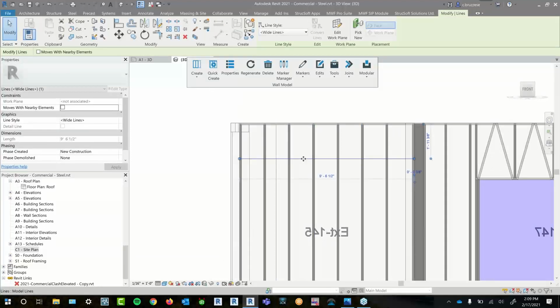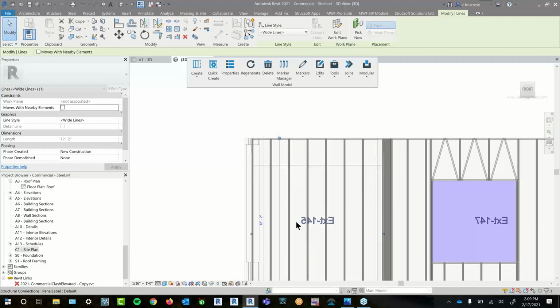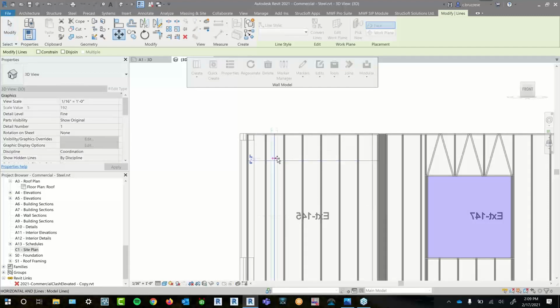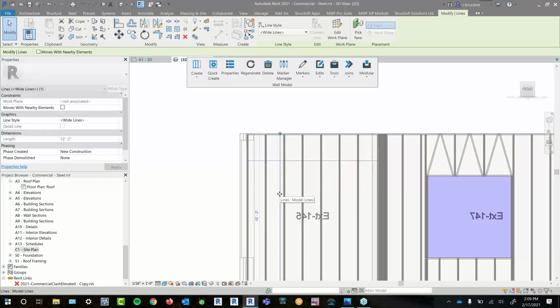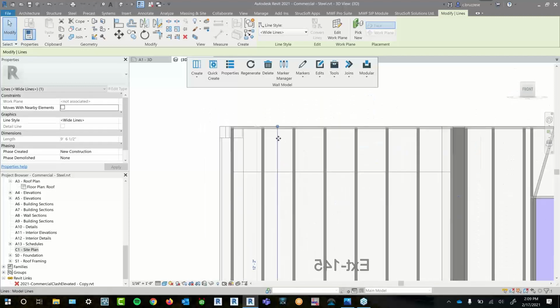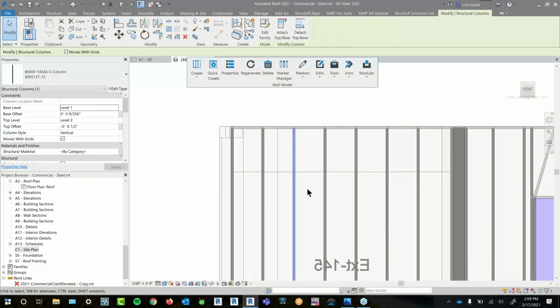And with the marker lines, it's going to populate initially with just the lines. And anyone, again, who's used the marker lines knows that you can take these lines, you can move them. So if you did want that overlap to be in a different bay, you can always shift it after the fact. They can be copy pasted, deleted, moved around. So you're free to use some Revit commands on these lines and move them exactly where you need to be.